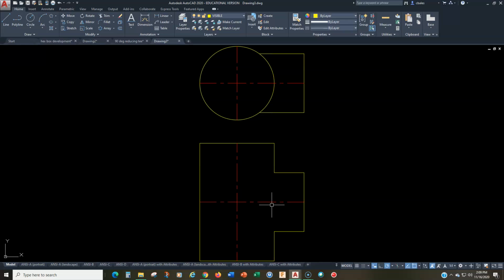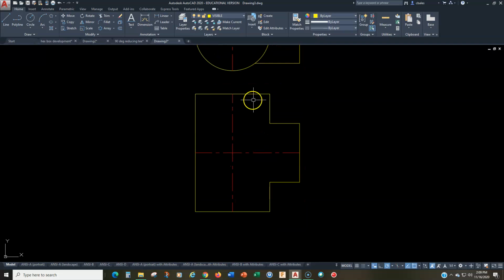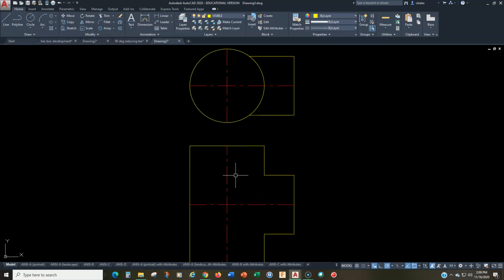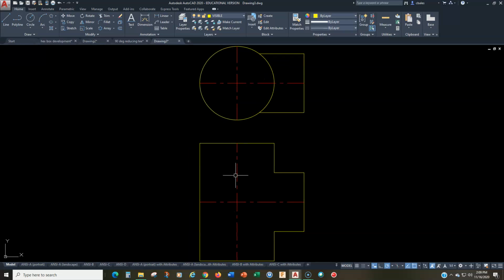Okay. So the first thing you got to do is you have to redraw what they've given you in the book, and that's what I have here. Okay, so we have a top view, we have the circular view of the vertical cylinder, and we have a rectangular view of the horizontal cylinder, and all the dimensions are specified here. And then also in the front view, all right. Now, again, like I said before, I kept these views purposely rather close together, just to make the drawing scale look a little bit bigger when I'm working on it.